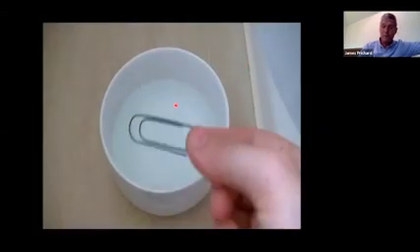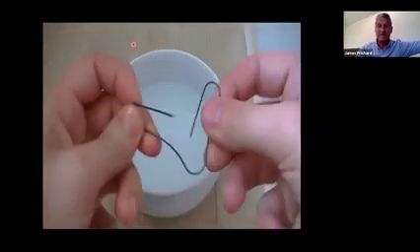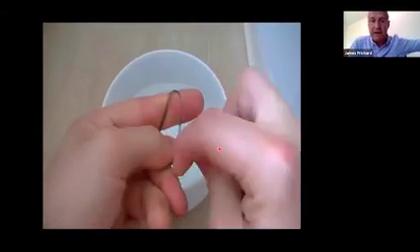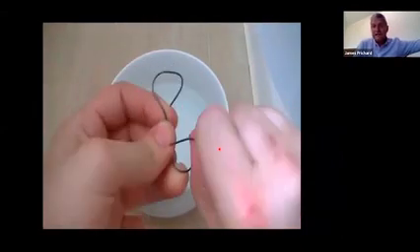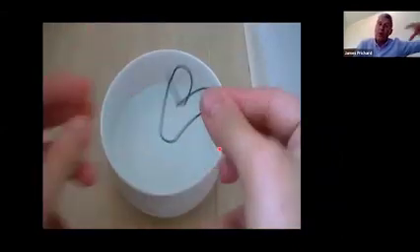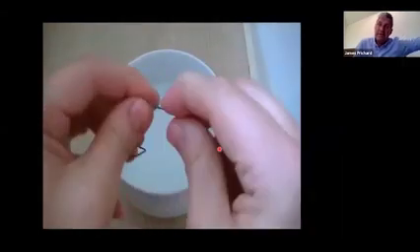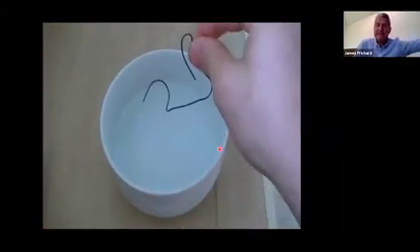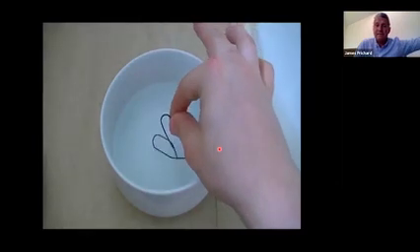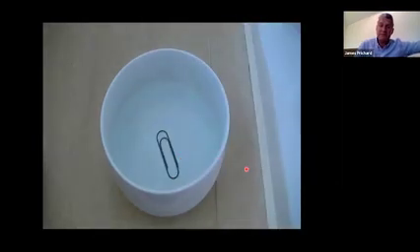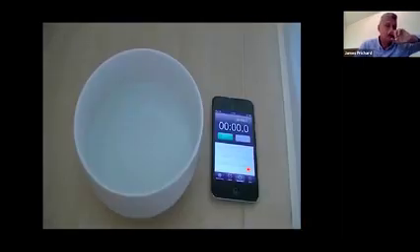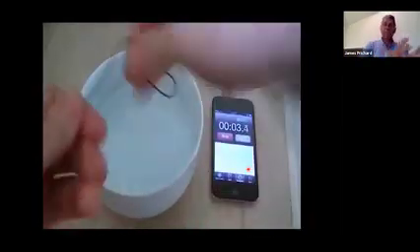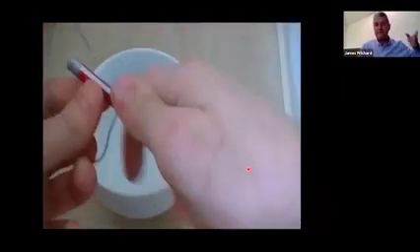So when we look at what controlled memory actually means, this is a martensitic nickel titanium alloy, and you can see that it can be manipulated out of its original paperclip shape. Now, the clever thing about this alloy is it can be made to be heat sensitive. So when the alloy is deformed, when you heat it, it can create a different shape. Now this caused us a problem with the original nitinol 55 alloys because when it deformed and you stuck it in an autoclave, it would reform and you couldn't spot where it was going to fail.